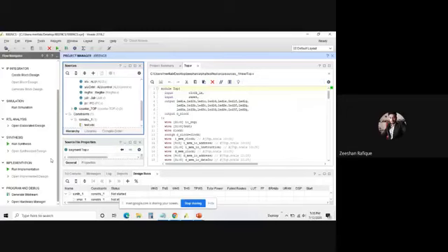After the synthesis process, you have to implement it. What does the implement do? Implement will take your XDC file, this one file, and port and reconfigure it according to your board you have connected with this tool. So at last there is a bitstream file. Just click on generate bitstream. It will generate your bitstream file.